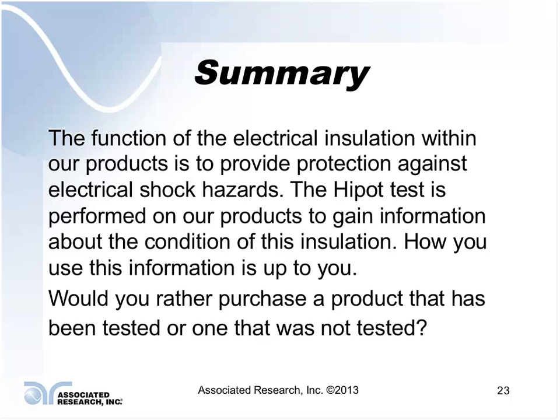Sure. In going through and doing a Hipot test, ramping is done for a couple different reasons. It may be done to make sure that you do not have an over voltage upon applying your test potential, where you could have a surge by applying your test potential immediately, depending upon the Hipot, so you don't have an overshoot that could possibly damage the insulation.